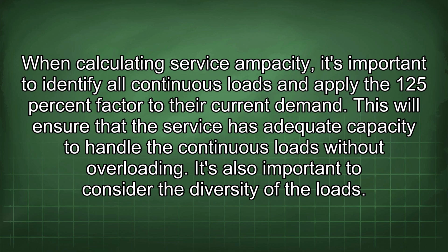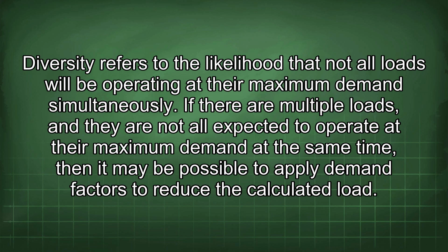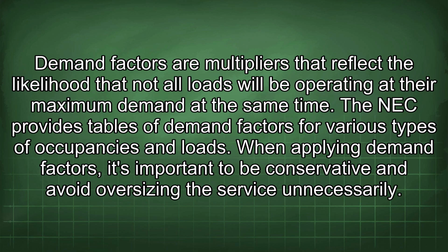It's also important to consider the diversity of the loads. Diversity refers to the likelihood that not all loads will be operating at their maximum demand simultaneously. If there are multiple loads, and they are not all expected to operate at their maximum demand at the same time, then it may be possible to apply demand factors to reduce the calculated load. Demand factors are multipliers that reflect the likelihood that not all loads will be operating at their maximum demand at the same time. The NEC provides tables of demand factors for various types of occupancies and loads.